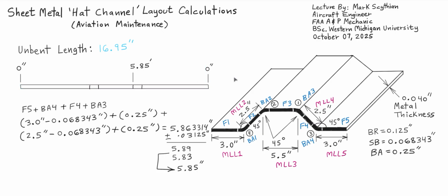We move the sheet metal section of 16.95 inches in length and place the right side into the sheet metal brake, 0 inch position and 0 degrees angle, and then we would implement a 45 degree angle bend downward. And again, you might have to bend it a little bit more than 45 degrees because the material springs back somewhat to maybe 43 or 42 degrees.